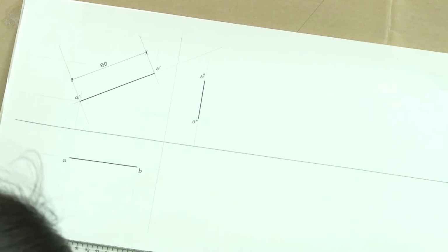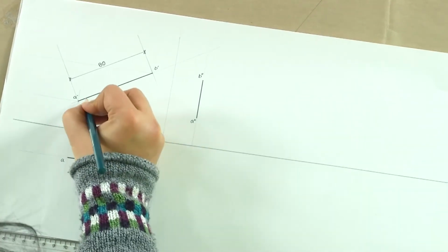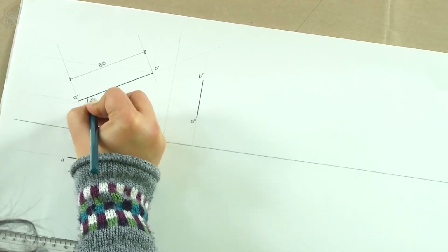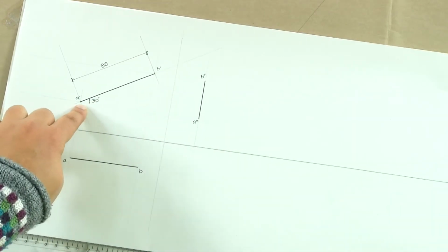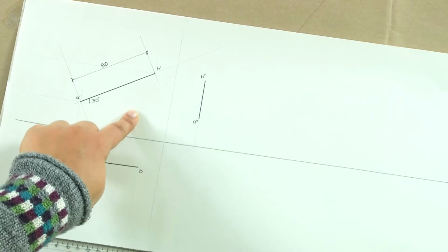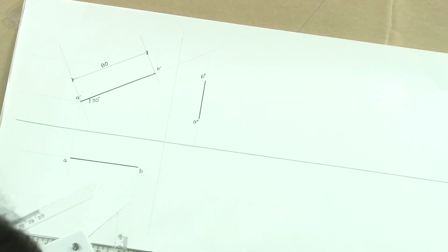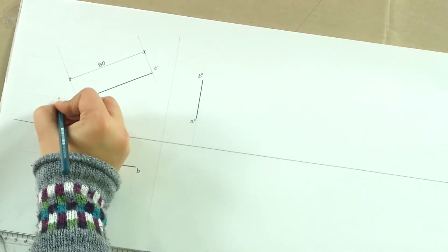The other thing that we had was this angle to HP. So, we will mark this angle to HP and we write 30 degree. So, it marks that there is an angle which this line makes to HP as 30 degrees. Then it says it is 3 centimeters in front of VP and lower point is 3 centimeter above HP. For this, we will have to draw a dimension line on the side to represent both these conditions.